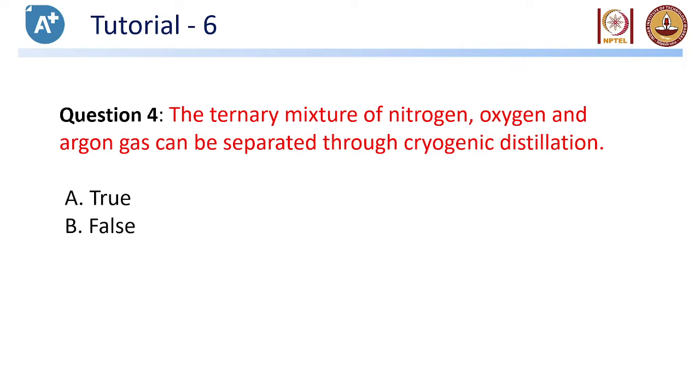That's the only difference between a simple distillation, like crude oil distillation, and cryogenic distillation. Except for the temperature ranges, everything else remains the same. Since nitrogen has 77 Kelvin and the others have about 86 and 96 Kelvin, all three have saturation temperatures of less than 123 Kelvin. Thus it requires a cryogenic distillation process to produce, separate and liquefy them.